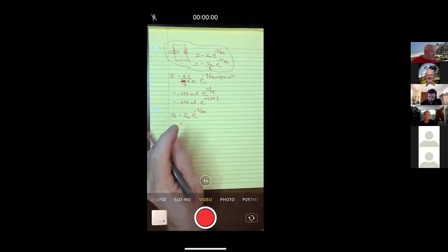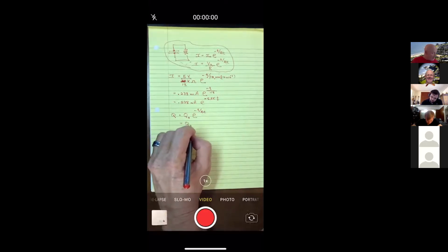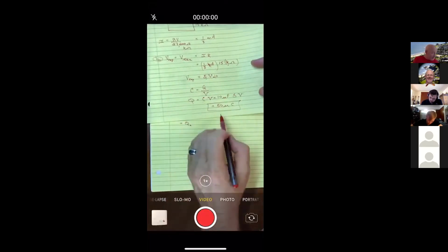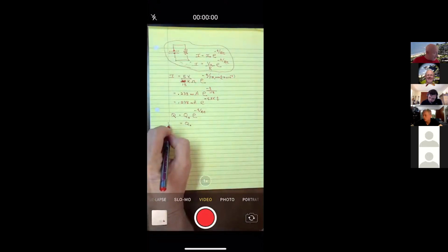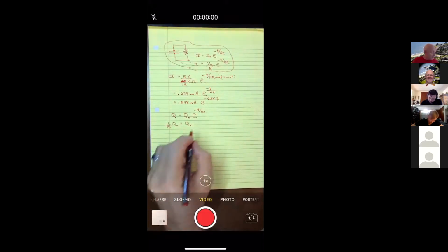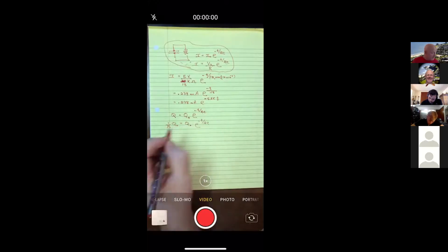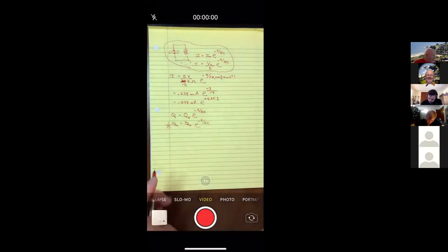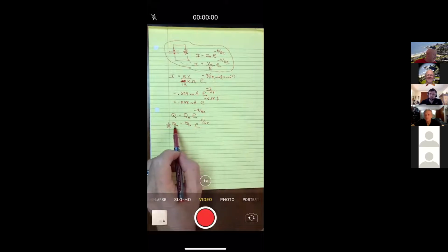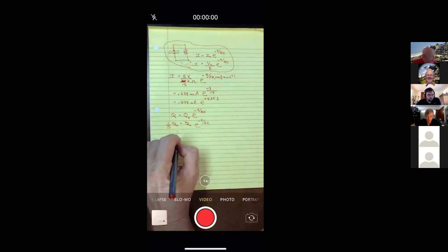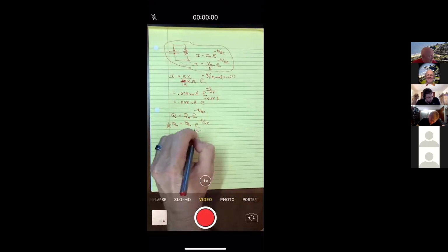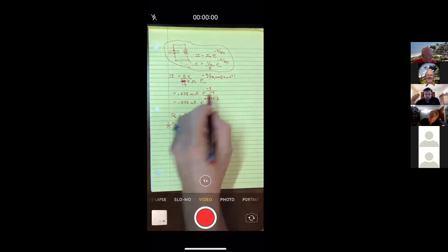And so it says, how long does it take to do 1/5? Okay, so I'm not even going to bother to put in what the initial charge is, although we did solve it back in part B for 50 microcoulombs. And the reason I'm not going to bother is they say to 1/5 of its original charge, and then the original charge is going to cancel off. You're going to get 1/5, which is exactly what you get had you put in 50 here, and 1/5 would be 10 there, and so you would go 10 divided by 50 and get 1/5. Okay, so this is 1/5. This is e to the minus t. And this R times C we did earlier as 0.18.